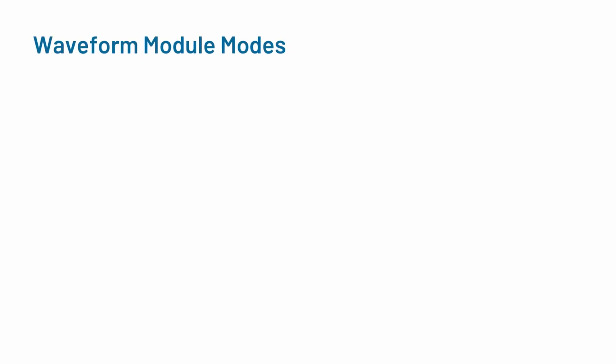Alright, with that said, let's now jump over and look at the waveform module a little bit more in detail. As we mentioned before, this is where we can control what happens to the event from an event module before it actually gets sent to the physical drive output. This includes things like the pulse width as well as how many cycles of pulses can happen per event that occur from the event module. We will look at these functions more in depth during our examples.